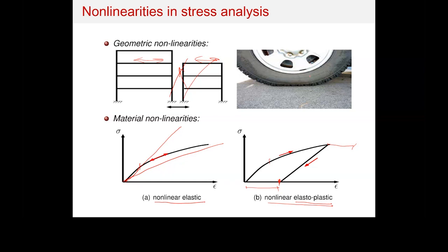It's not just that the pressure of the tire would change, but this very flexible material at some point, because of the cyclic loading, is going to lead to fracture due to the fatigue you have built up in the history of this material.